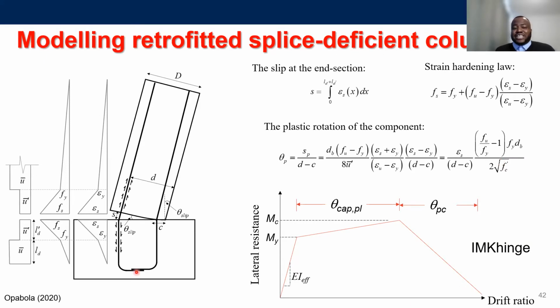Because don't forget, what you're dealing with here is strain penetration. So you are able to assume some form of average bond in the nonlinear and the linear phase, and that is incorporated into this model. However, if you're going through a different approach, the recommended approach is to use the Priestley equation of 0.044 fy db, which also does a relatively good job. But I should point out that that formulation was developed using bars with a yield strength of 300 MPa. So when you're looking at some other yield strength, there's a possibility of your answer deviating from this. But I think we can spend another hour talking about that, because there are lots of studies on this already.